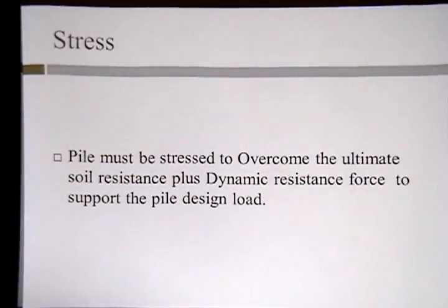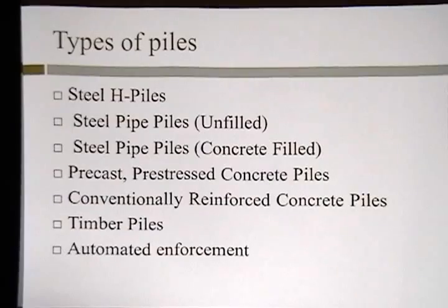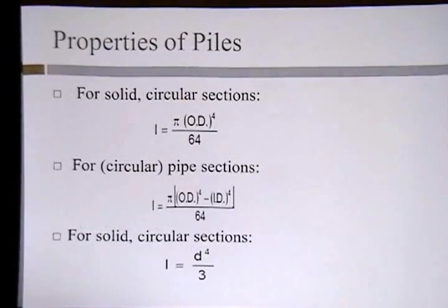The high strain rate and the temporary nature of the loading allow a substantially higher stress limitation than the static design case. Based on the type of pile, the pile material ultimate strength must be greater than the ultimate pile soil resistance. Therefore, the factor of safety is applied to the material strength to obtain an allowable stress.